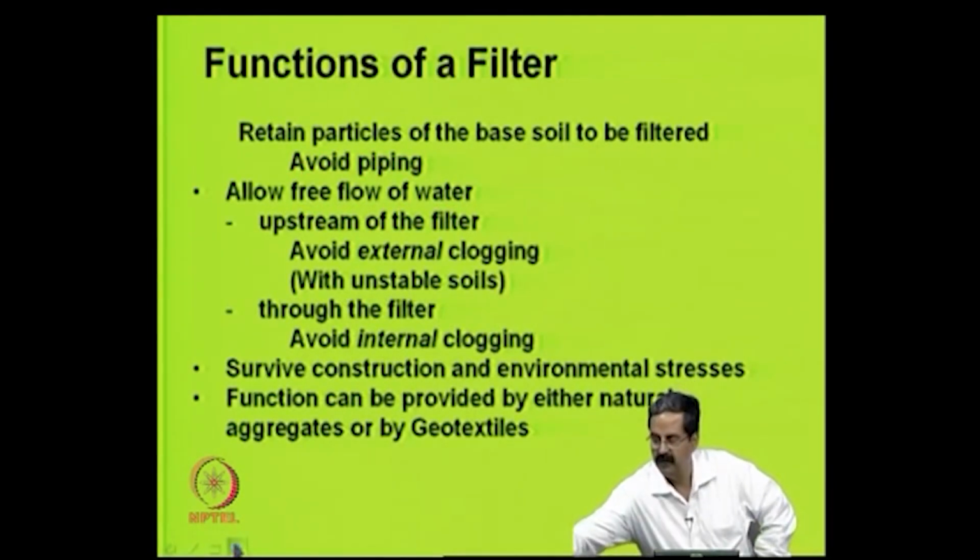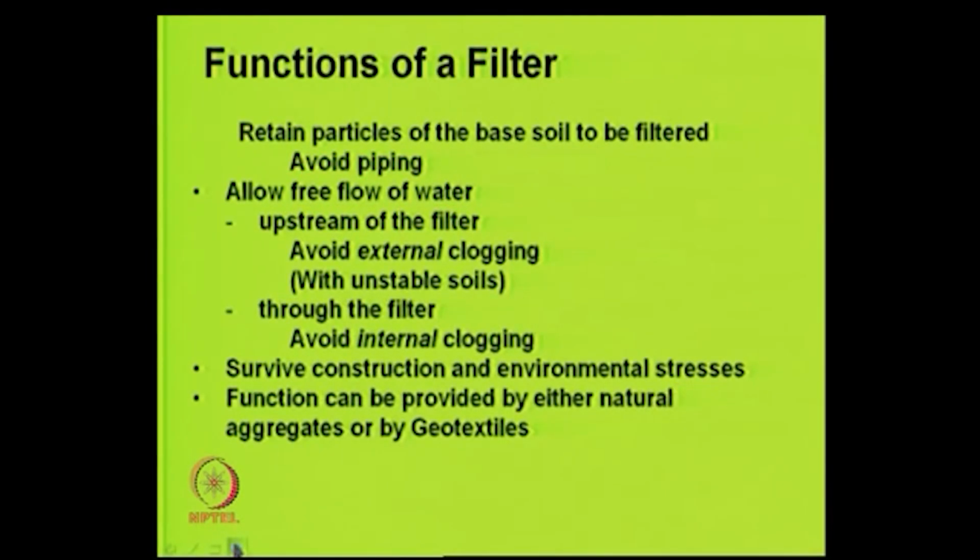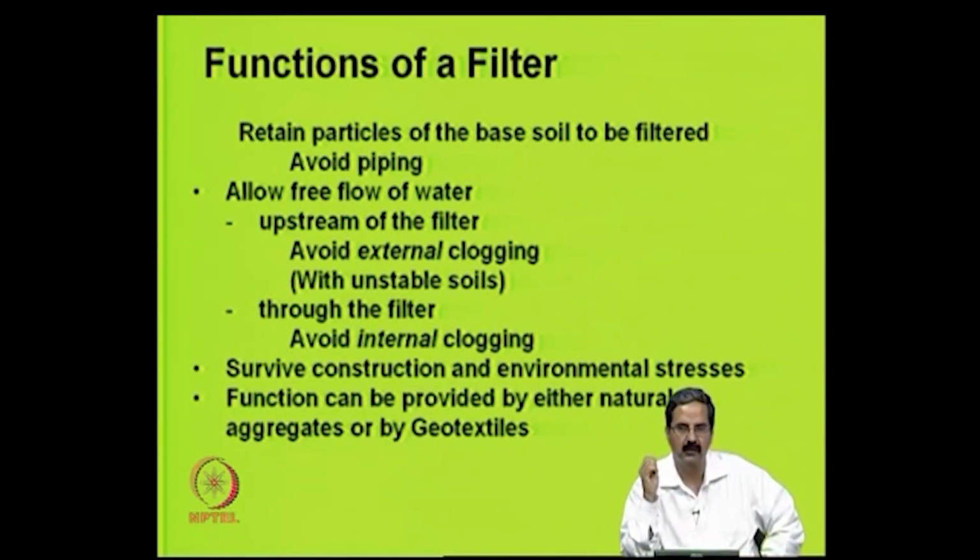So, when do you need filtration? We need filtration when you want to allow water to go through a particular system. For example, the water behind a retaining wall: you would like to see that the water comes out of the weep holes properly, and that there are no pressures on the retaining wall because of the water.